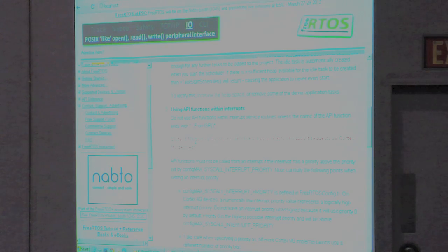I would say it's a very important point that if you're creating a FreeRTOS project, please don't try and do it from scratch. The whole concept of this is that every port comes with a pre-configured demo. It has all the correct source files included, it has all the correct configuration, it has the configuration file for you there as well, it has all the correct compiler options and that sort of thing.